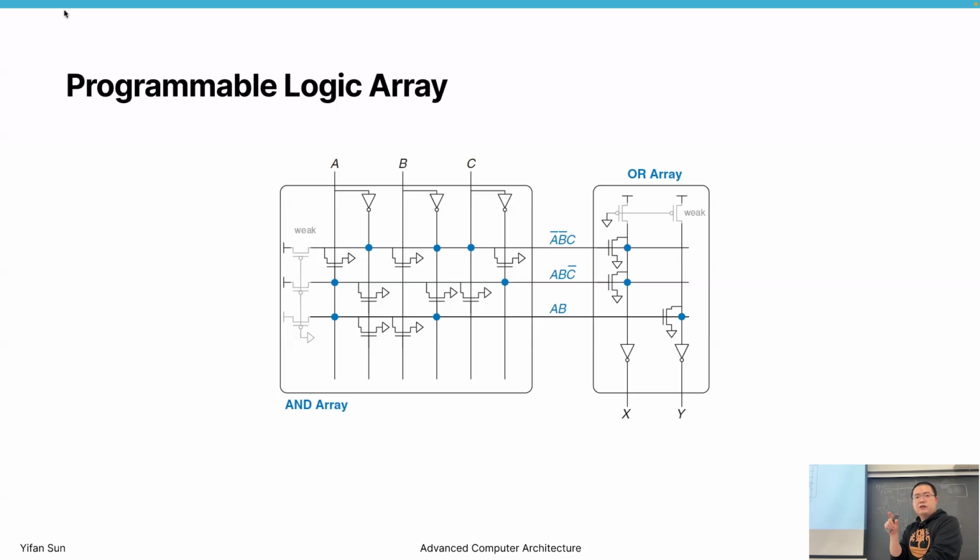Verilog and VHDL are languages for hardware design. They describe what type of logic you want to perform. For example, you want to have two values added together. In this case, software will generate the truth table for all possible inputs and generate this type of lookup table, or this type of simple logic array, for you. But these simple logic arrays are only for combinational logic, right?